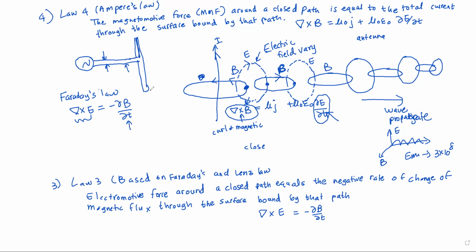There has to be a return path. Single wire means like in phones and so on. Now, that is a microstrip antenna. This antenna will be on the top conductor of the PCB. The PCB has a ground line, so the antenna will be on the top conductor, and the ground plane will be the return path of the currents.